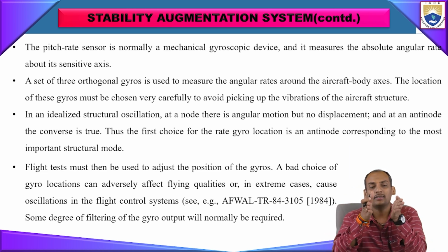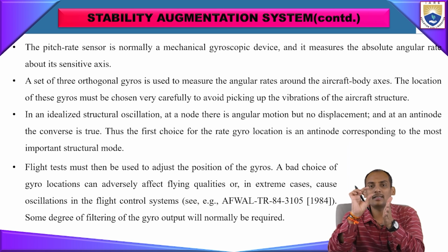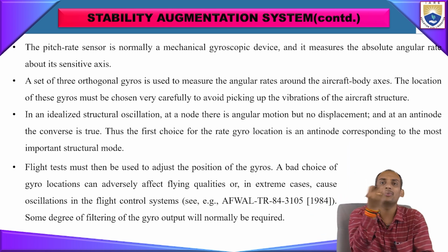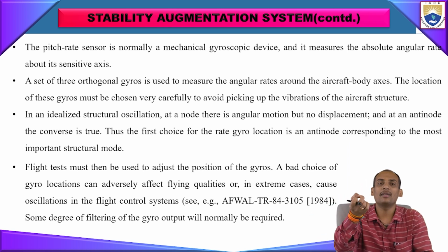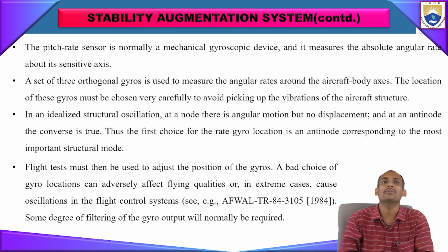If you want to move just 2 degrees of pitch, it accurately measures that value and gives the feedback to the summer, so that the summer will automatically cut off the signal, and the pilot can get the feedback from the control system, so that we can stop our control, and after that we move forward.